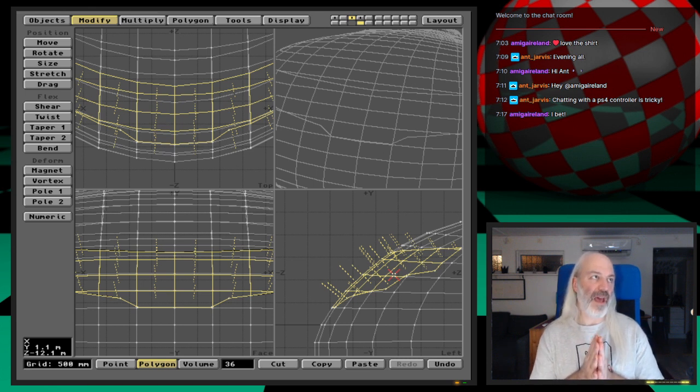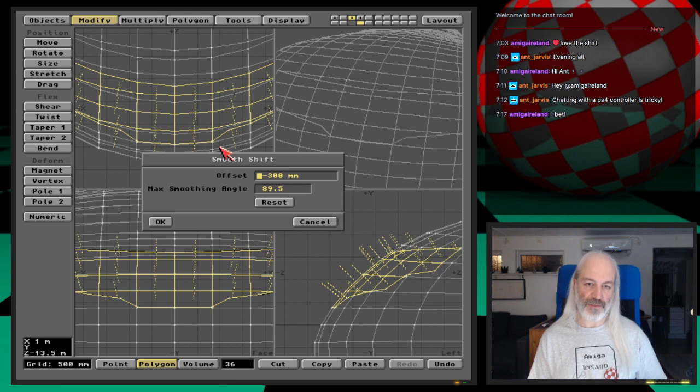Create, say, how do you say that? Let us smooth shift it so that it will look quite towards the inside of the rest of the object, so it will look carved, or more inwards. So let us invoke smooth shift. Now that should be very subtle, because we have lots of polygons and a lot of things can go wrong here.